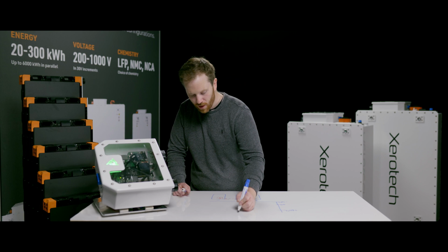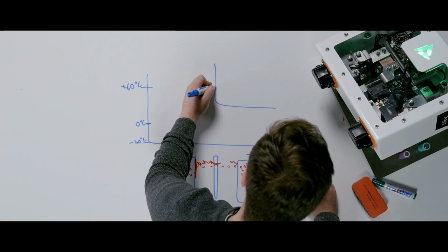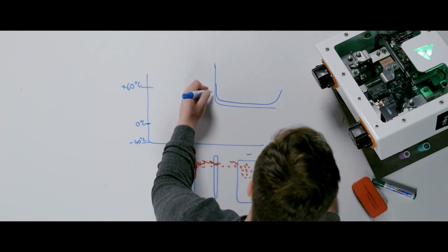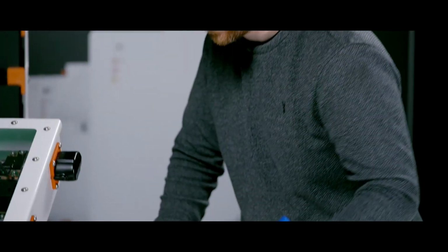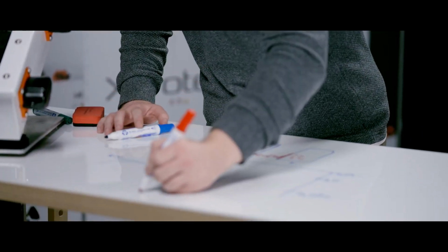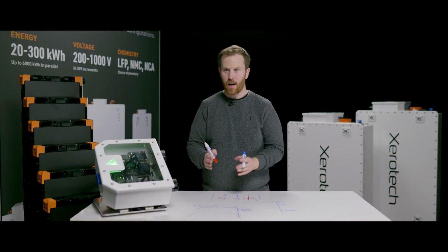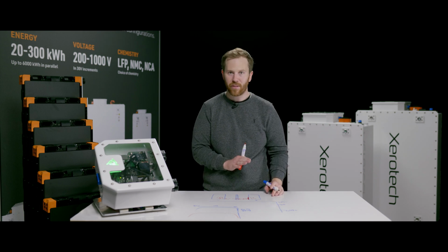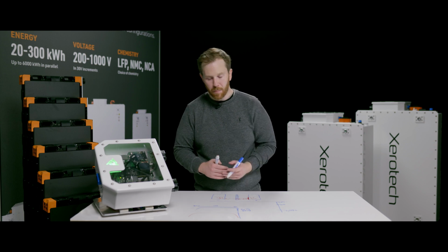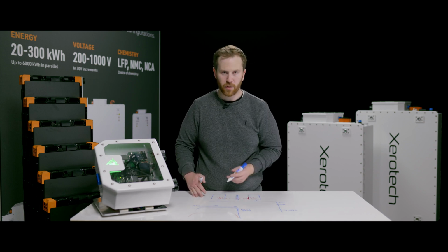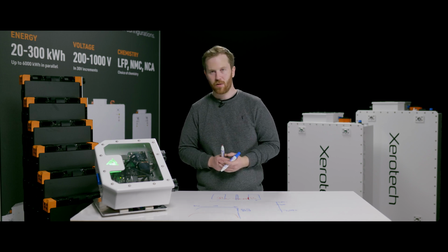And that comes back to our DCIR curve, our DC internal resistance. You might remember this bathtub type curve here. So this is going to be across the SOC window. At lower temperatures, this curve is much higher. So basically the batteries have high resistance, and when they have high resistance, it limits the amount of power they can discharge until they heat up. But as the battery is discharging from this cold condition, it tends to self-heat. So temperature is incredibly important in terms of batteries.